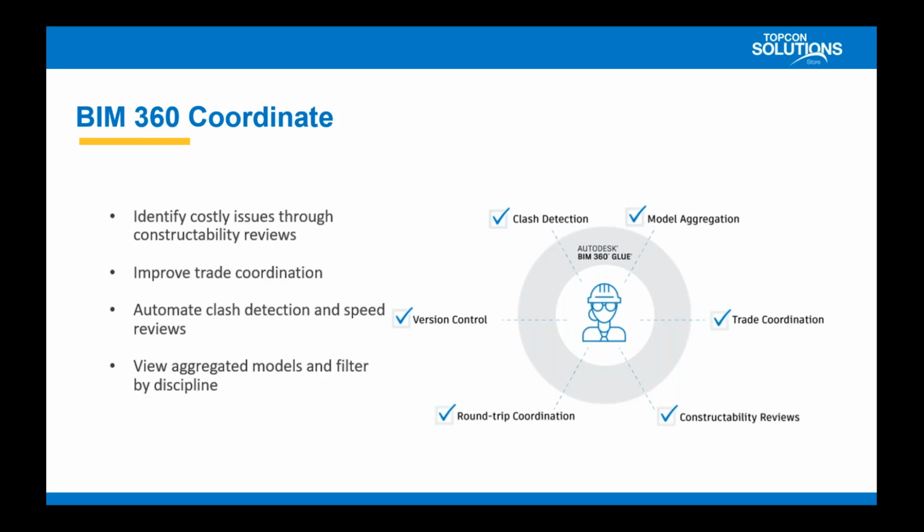Now, another great thing about this is if it's coming over with that model data, right, the metadata from Revit in this sense, typically when we see these clashes, they're going to have the ID numbers for those specific families that are clashing. So again, making it easier, not just for, let's say, the construction teams, but also maybe the design teams to navigate to that and get it corrected, right?